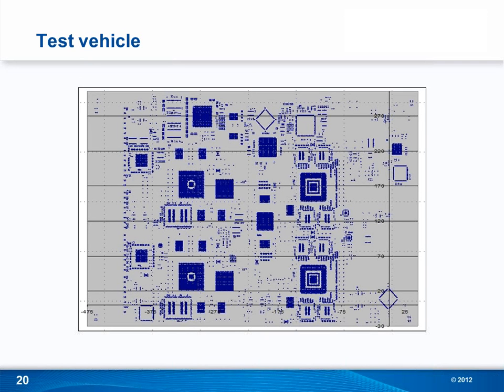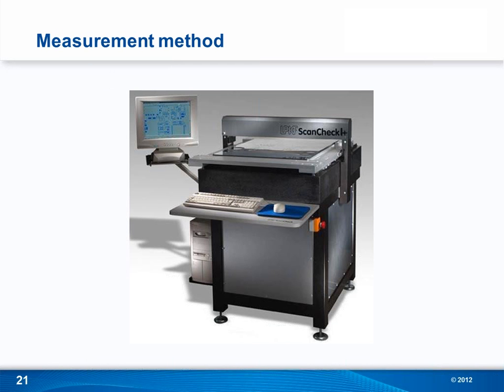So Anna, once you ordered the stencils and got them back, how did you check to see if the aperture sizes for all those 21,000 apertures on each stencil were as desired? Well, in my case, that was easy. There's a system that I'm depicting here. It has a glass plate on the table that moves underneath the light bar, which is on top.